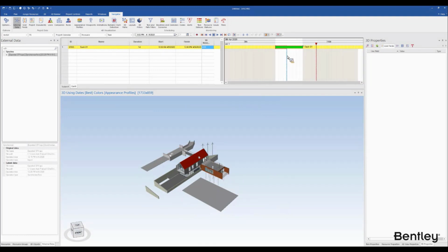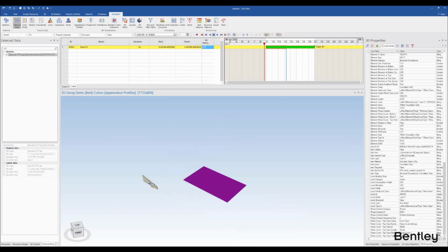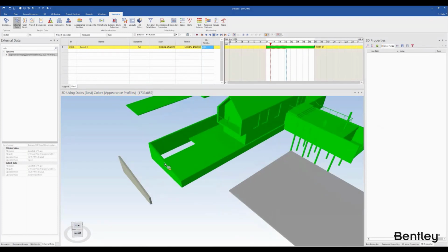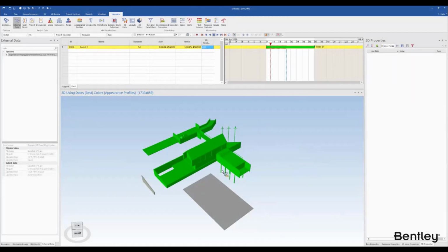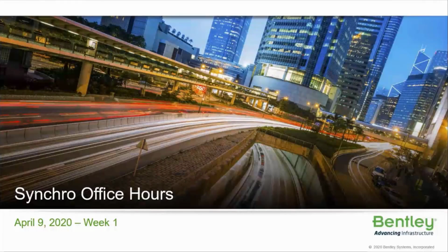Now if I move my focus time before the task starts, you can see the new objects were not assigned to anything and they're still floating around. They're not assigned to a task, but the model elements which had moved or changed their profile are still connected to the task. So that means our synchronization, all our relationships between the objects, the resource, and the task, are being maintained.